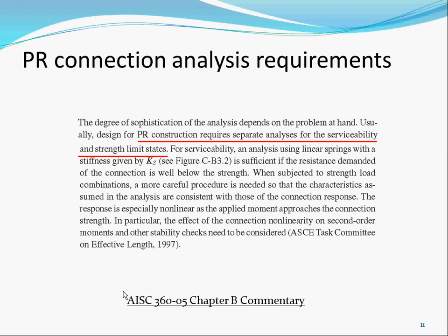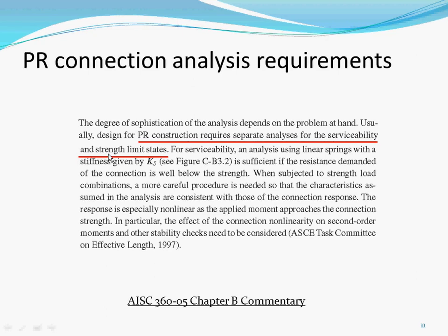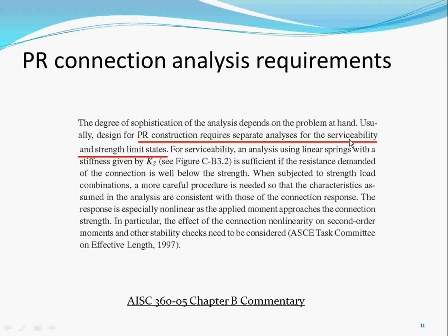Some more commentary: PR connections require a separate analysis for serviceability and strength limit states. What they mean here is serviceability is typically for your drift check, for your deflection check. Deflection and even drift, they consider that serviceability. For strength, the question is how much strength do I need, like moment, shear, and axial. Can my connection take all the load from these cases? So you need a separate analysis for the serviceability and the strength limit state.